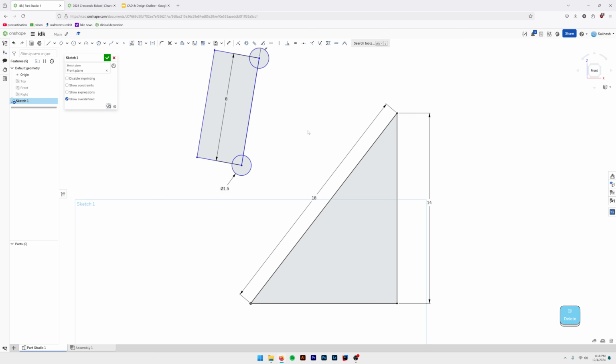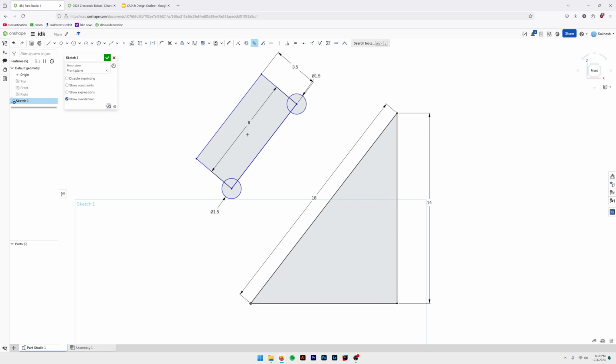Or we could do the cooler way and go up here to our parallel tool, or you press B, right? I haven't fully memorized the sketch constraint ones yet. It'll come with experience. Over here and over here. Oh, well, I misclicked that, but yeah, look at that. So now I created a parallel sketch constraint between this line and this line, and you can see when I highlight over these sketch constraints, notice how it shows the relationships that it made.